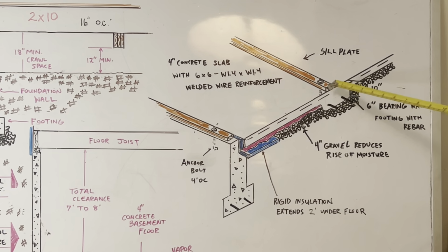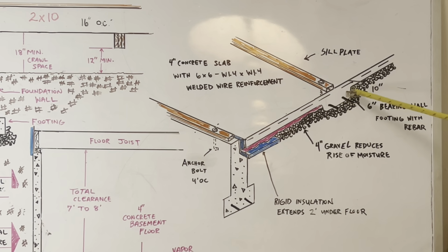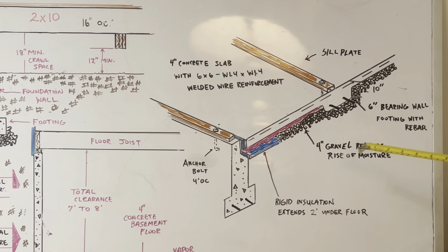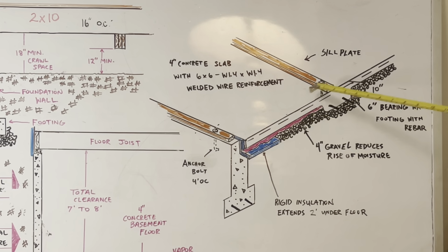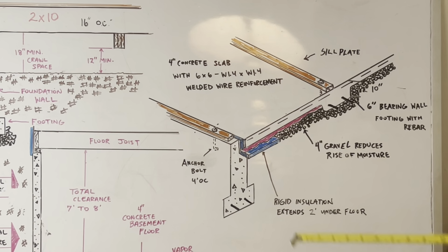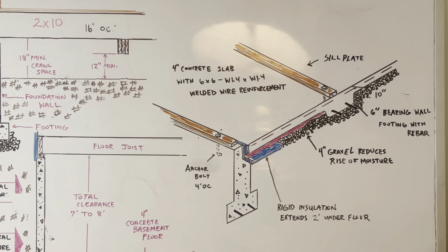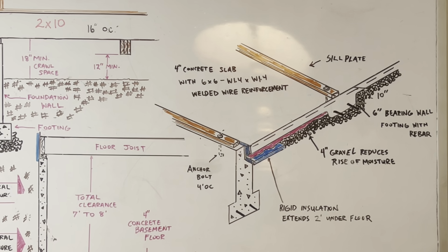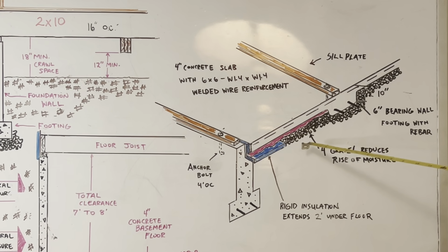Now it's thick right here because we're going to have a wall. It's going to be our interior wall or partition. So you're going to make it thicker right here under your floor slab. The slab surface is level with the top of the foundation wall in a slab at grade foundation. You can see that. In a slab at grade foundation, the floor slab receives its main support from the ground. So the main support, what's holding this up, is the ground.